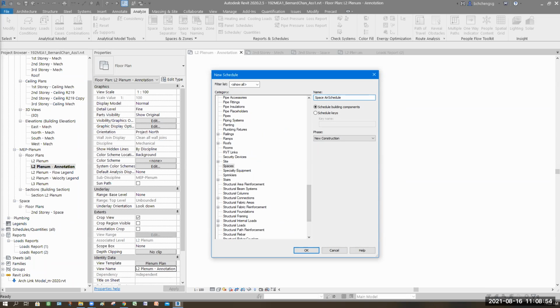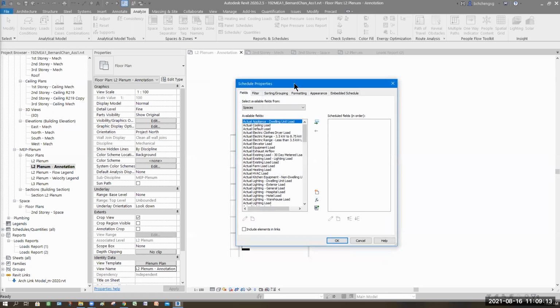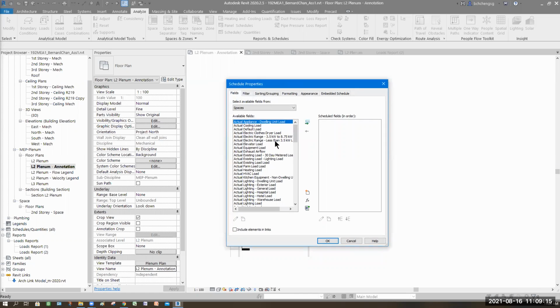Without the calculation, the airflow will not be accurate. Remember just now I said 718.2 from your report. So later make sure you choose the correct report. Based on building component, new construction, you click OK. Then filter, see what loading they require. So here, what did they mention? Double click the level, because every floor is different, since we are doing level 2 only. So level, followed by the name and number, which means whether it's the library or room 219.